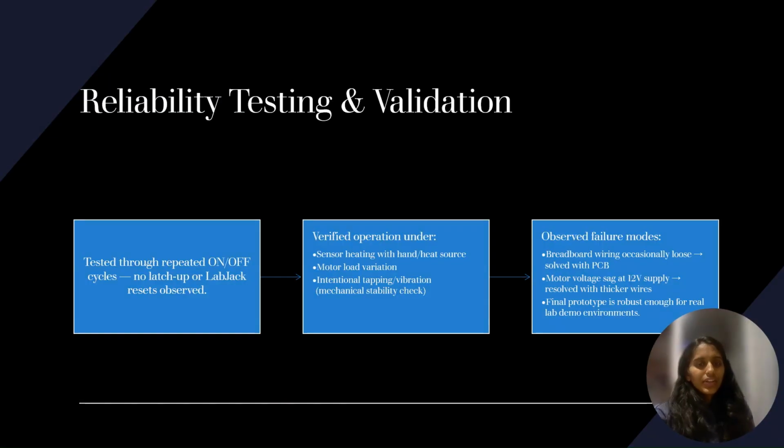Reliability testing and validation. To verify that the system was working properly, we performed several reliability tests. We tested the temperature sensor response at different room conditions and confirmed that the fan always turned on exactly at our threshold. We also checked the emergency and reset buttons multiple times to make sure they respond correctly and instantly.